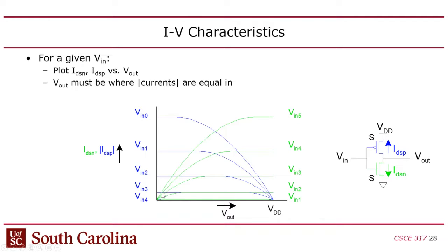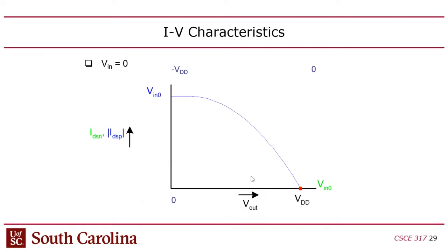So these lines will meet, right? Wherever they meet on the vertical axis, the voltage of the PMOS and the nMOS will then be different for each of those meeting places. So I'll find the intersection here, and I'll find the corresponding intersection over here, and this will tell me both voltages.